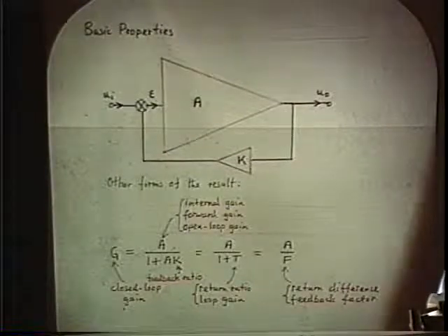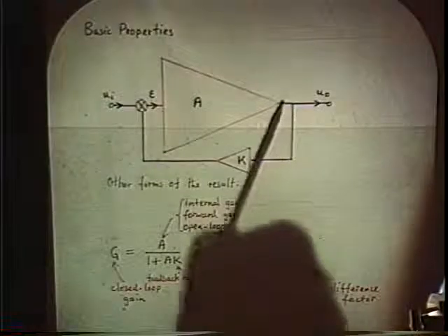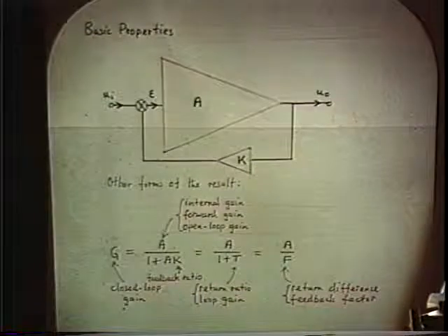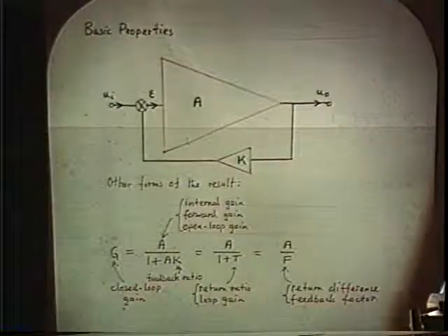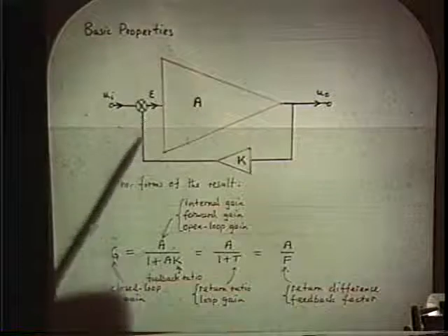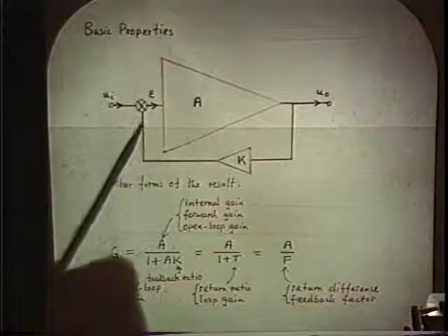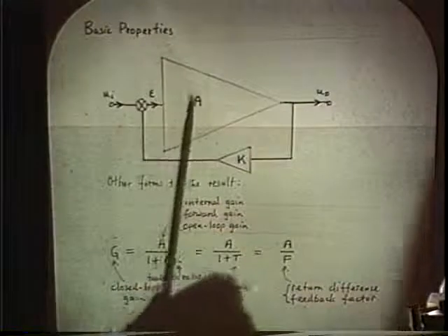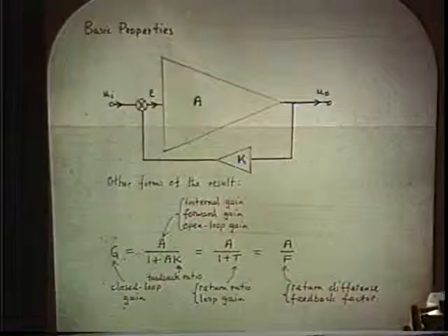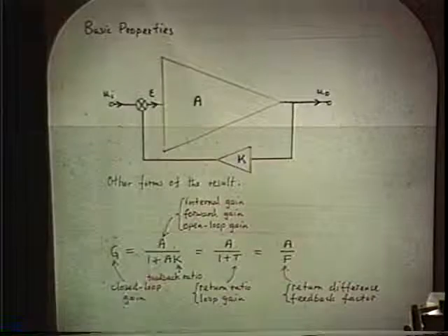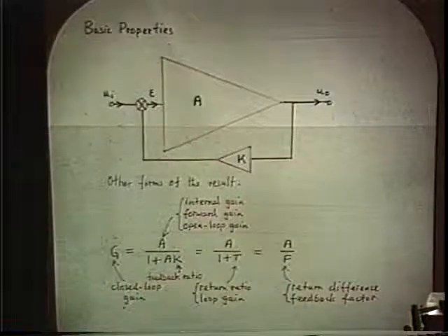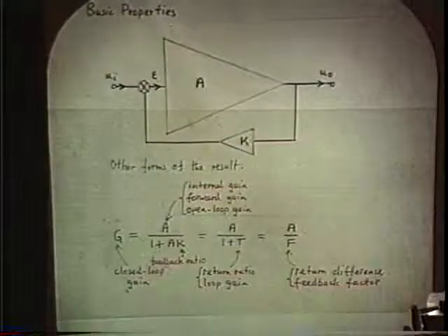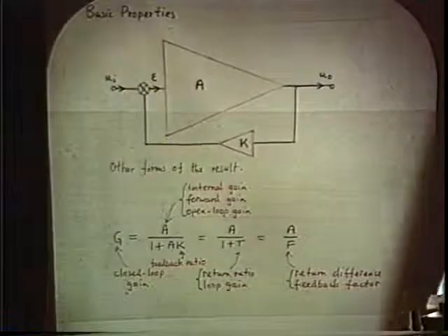partially. It's easy to know what to hang on first. It's not so easy to know what to do with the other end of the impedance that you're hanging on there. And exactly the same thing is true at the front end. If you disconnect the feedback at the front end, you also upset the loading. The result is the A that you calculate is not the proper value of A that belongs in the formula. That's why you get the wrong answer. That's the problem with that format. That's why I call it lousy.